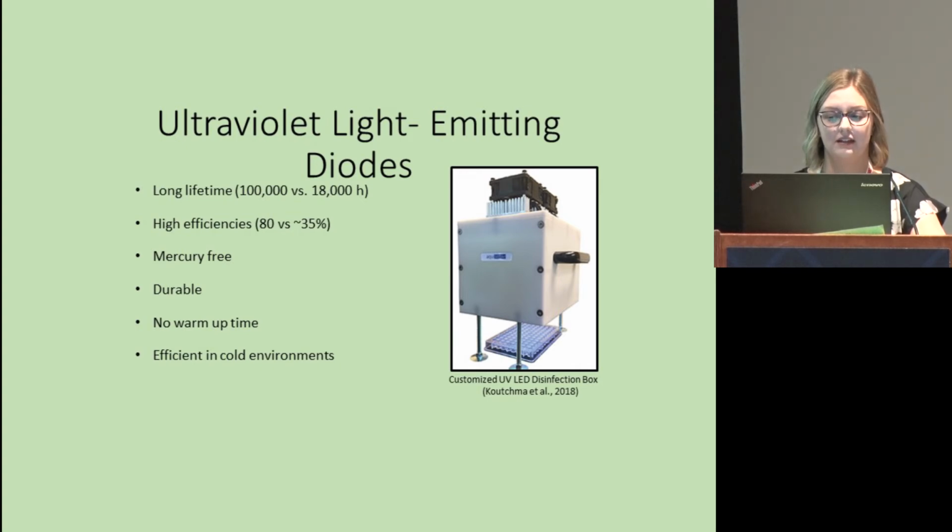And there's vacuum UV, which is from 100 to 200 nanometers. Most effective from a bacteriological standpoint is certainly UVC, especially at wavelengths of 250 to 270 nanometers. UV light can inactivate bacteria, viruses, cysts, and molds,